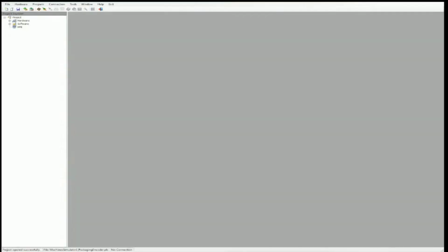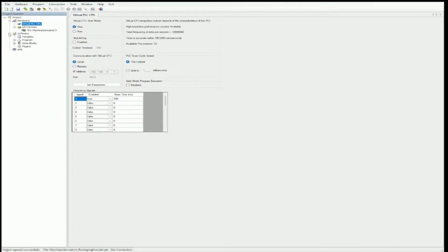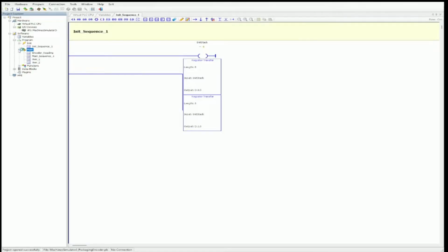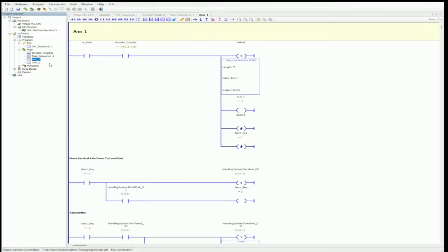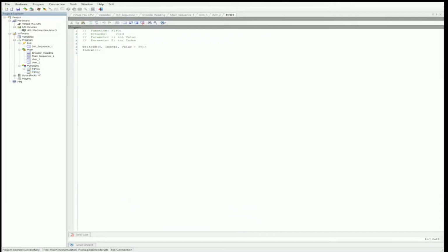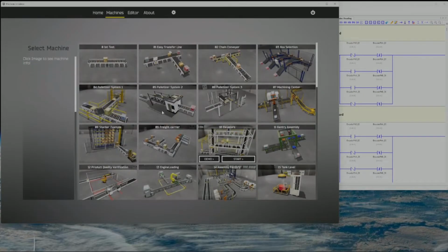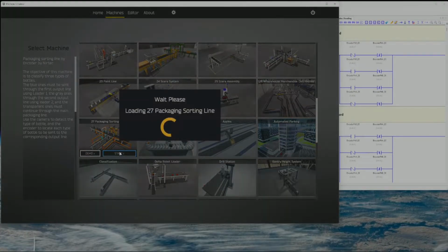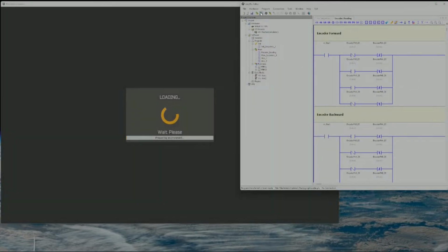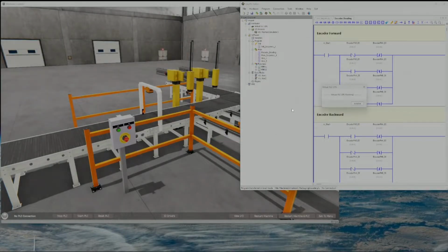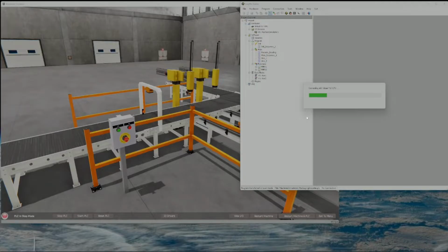To carry out the PLC programming, we will use EasyPLC, the PLC emulation software included in the EasyPLC software suite package, but any other automation software can be used. First, let's see the machine in operation, locating each of the key elements. Using this system, we can see how with only the encoder and appropriate programming, the position of each element that enters the conveyor can be known to the millimeter, based on the resolution of the encoder.